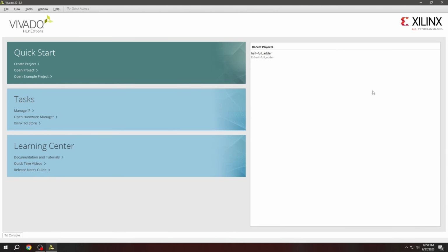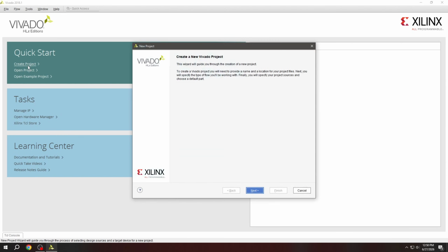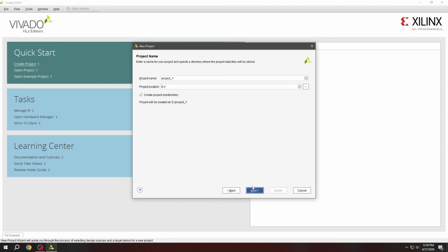In today's video, we are diving into digital design by using AMD Xilinx Vivado to build basic logic gates. Let's start from scratch. First, you click on Create Project and you click Next to proceed. In the project name window, you have the project name and project location. You can rename the project here and change the location in project location.